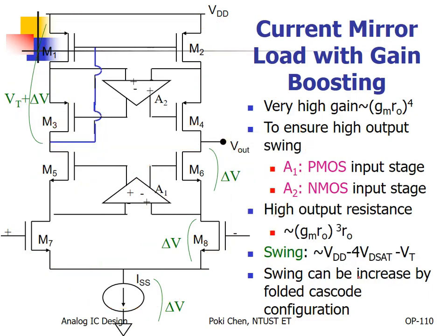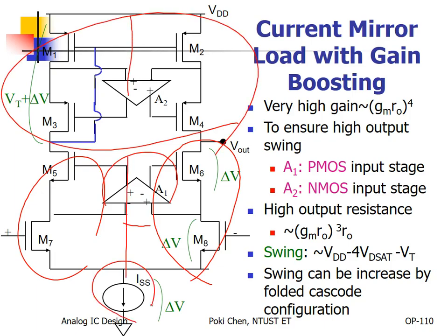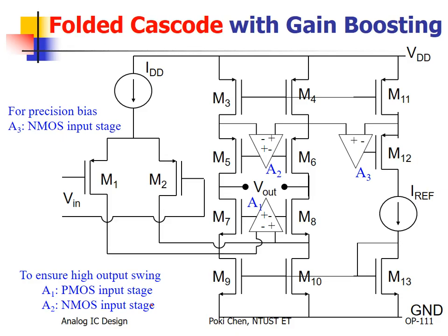And this is the overall structure: 1/4, 2/4, fully differential to drive both, and the counterpart circuit. In the middle, apply such kind of bias current. And again, wow, you see, folded cascode again. What's that? The major purpose, never mind high swing cascode or folded cascode, is the same: similarly, to enlarge your output swing. This is the so-called folded cascode. Later I will explain.